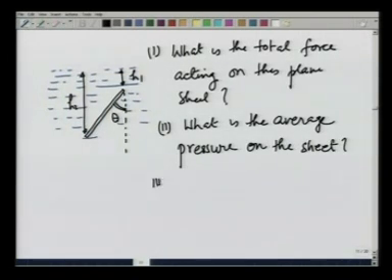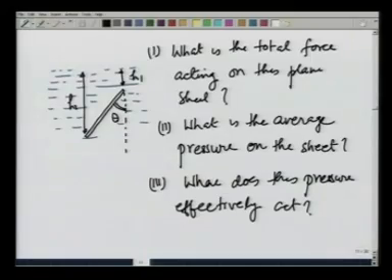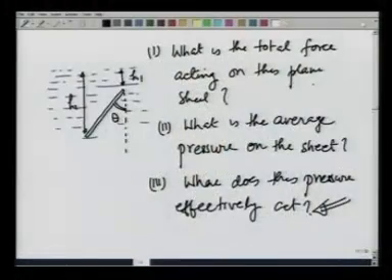And third, where does this pressure effectively act? What we mean by that is, where should I apply an opposing force equal to the total force applied by the pressure, so that the moment is also balanced. Somehow you can feel that the centroid is going to be involved in this, some area is going to be involved in this.